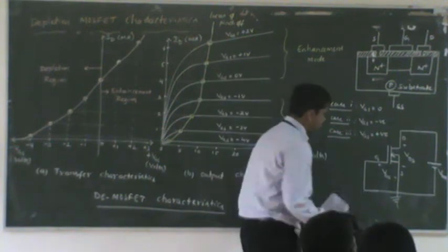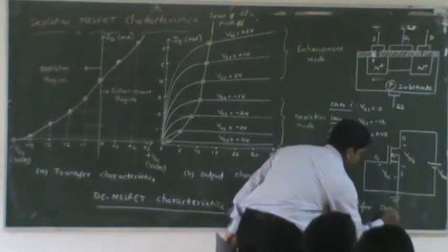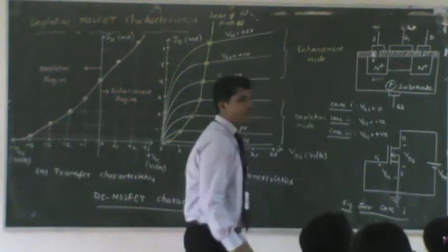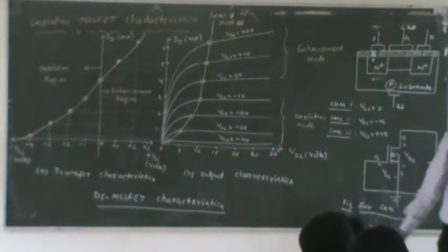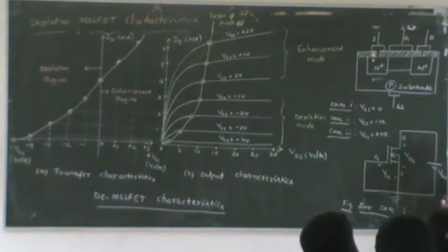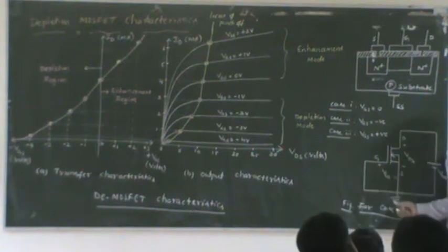So for the first case, the circuit diagram for case 1 is here, where you can see that VGS remains here. In all these three cases, we assume that there is some VDS. You can see VDS exists because of the connected power supply. VDD stands for the drain power supply, which is similar to the VCC in case of a BJT. As long as you apply it here, there will be some drain to source voltage. But VGS is important for us.